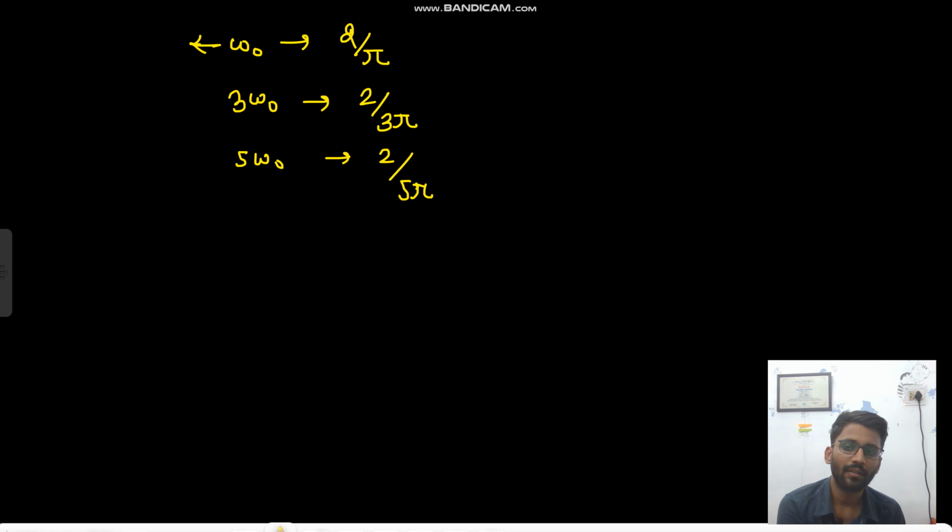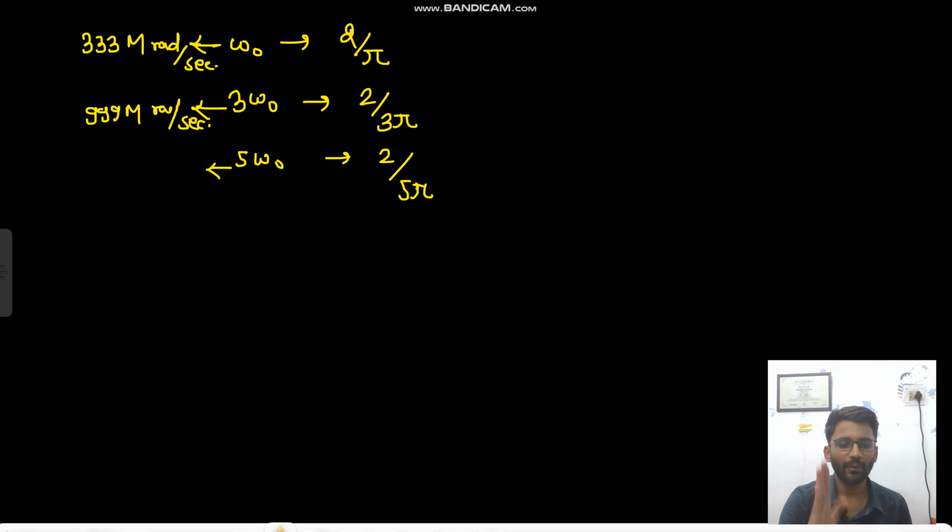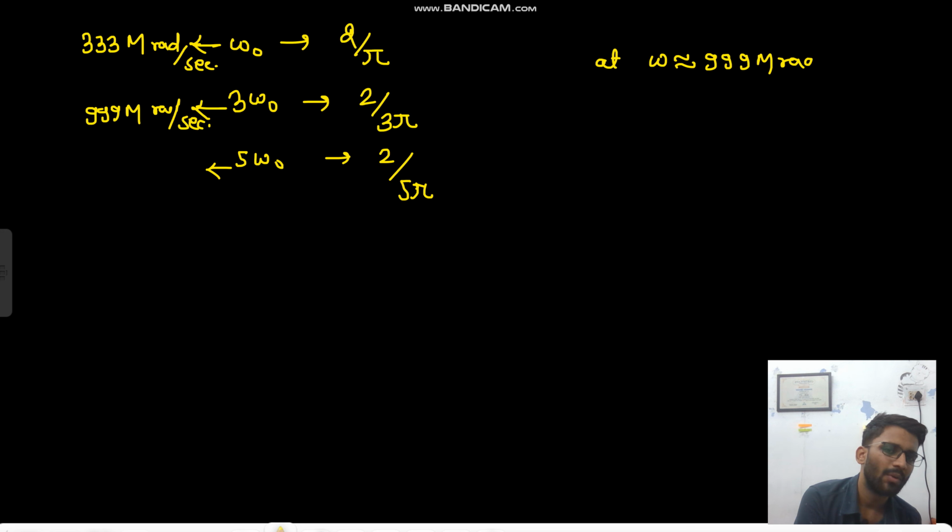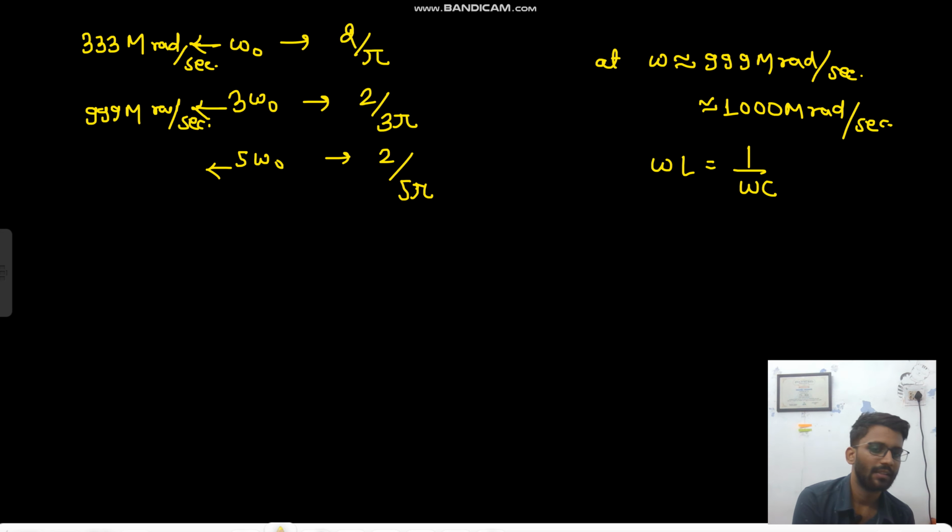What is the value of omega naught? 333 mega radian per second, right? What is the value of 3 omega naught? 999 mega radian per second. Okay. Now what did you see? The voltage amplitude at omega equals around 999 mega radian per second, or you can say 1000 mega radian per second. What did you see is that omega L is equal to 1 by omega C. Okay, that means your V naught will be I into R, that you saw, right?